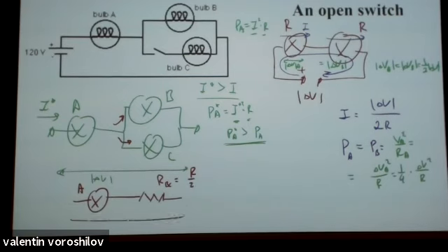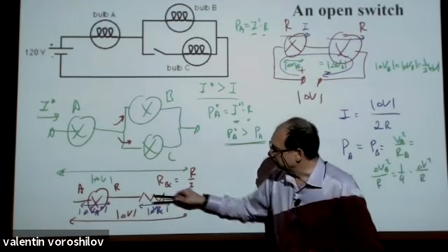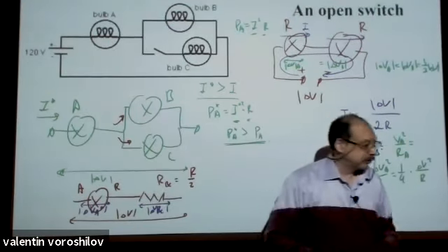And now we have to apply the same voltage as before. So what do we see here? Well, we see that now the voltage A star, the new one, and this voltage BC are not the same. Which will be higher, which will be lower? Well, now in this circuit, they share the same electric current. So same current, more resistance, more voltage.